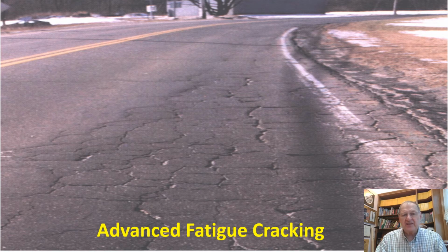Now, I didn't take this picture, but this is a rural highway that's got some problems with drainage. And so even though this picture was taken in the wintertime, I'm certain at some points in the year there is water that ponds in this ditch, and that water is soaking in underneath this pavement and softening the subgrade. So why is it cracked here and not cracked here? The difference is the amount of deflection. It's the coat hanger thing again.